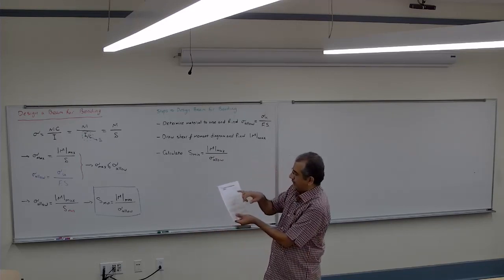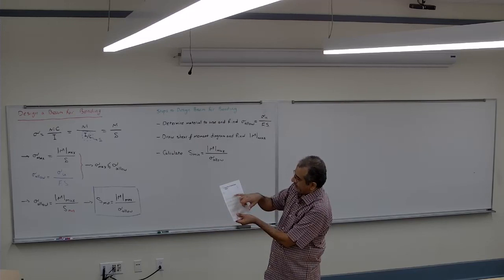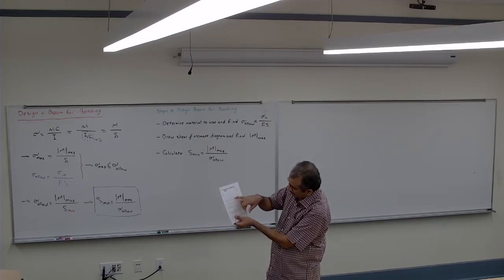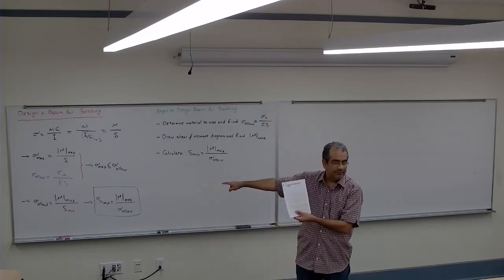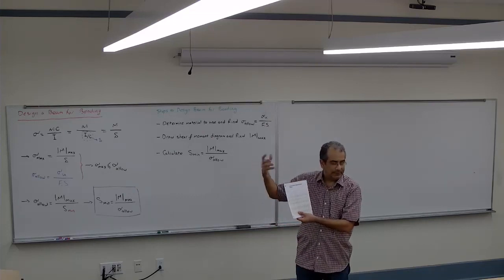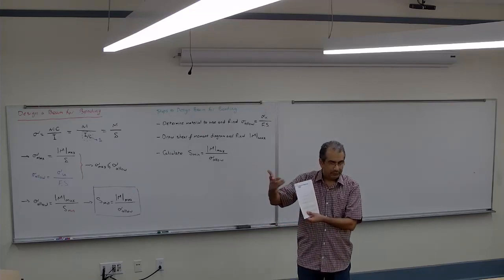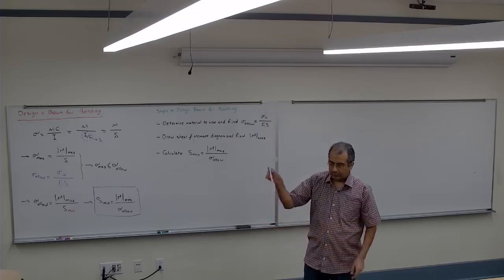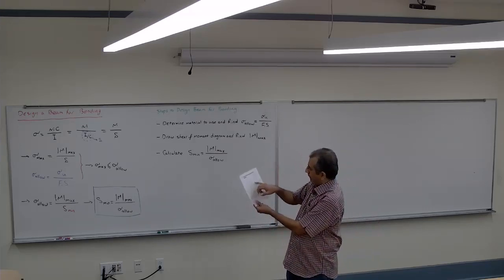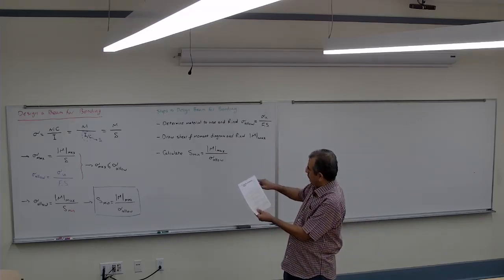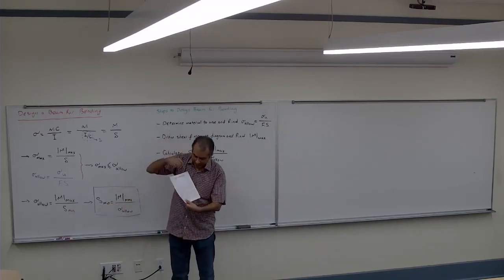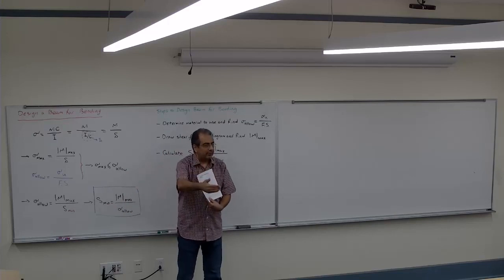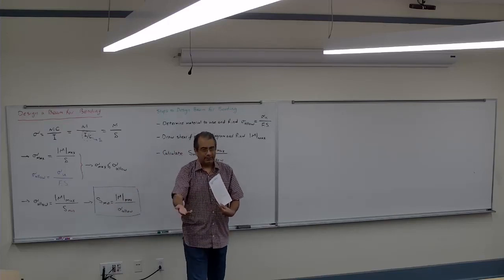the width, the thickness, all dimensions, and then they have the moment of inertia, and then they have the S. Then you look at the S and find the S that is larger than that. That's going to be your steel beam. So if you are dealing with a steel beam, you go to these tables and locate the S. For example, if you calculate S is 100, you find the one that is just above 100. That's going to be your beam.